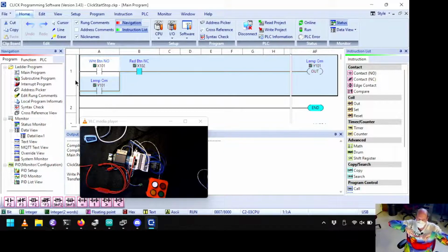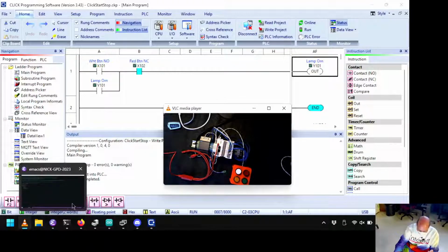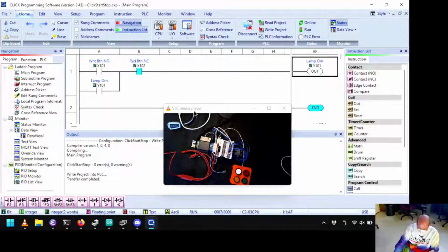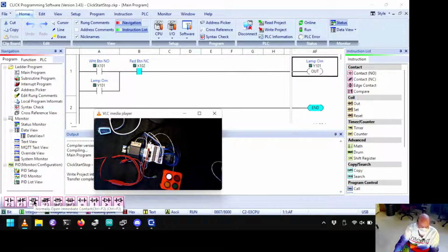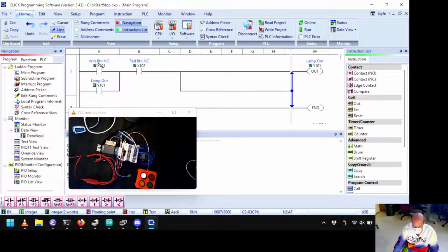So you can have combinations of things that wouldn't make sense in an electrical schematic, like assigning to the same coil more than once, or having an output that, when triggered, turns a coil on in one direction, but it isn't a continuous thing, it just latches it on, that don't exist as electrical components. So for example, down here, there are rising and falling edge detecting contacts that can be in your ladder rung. And you can draw lines between things and insert additional circuit components.